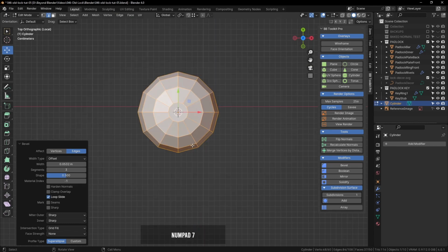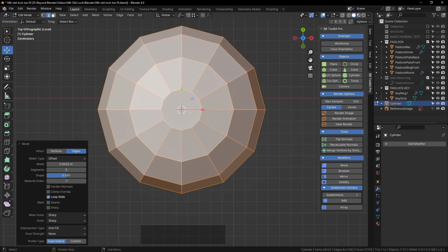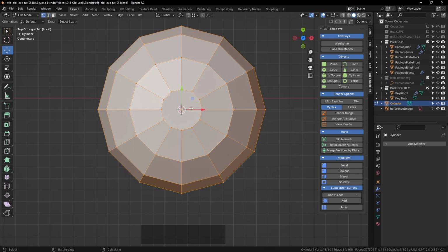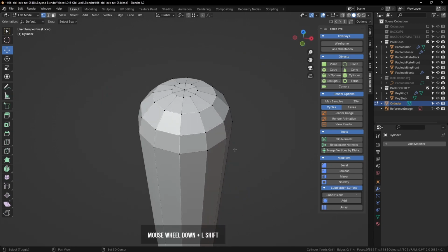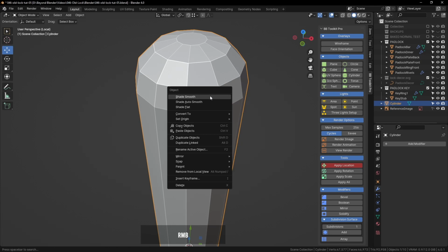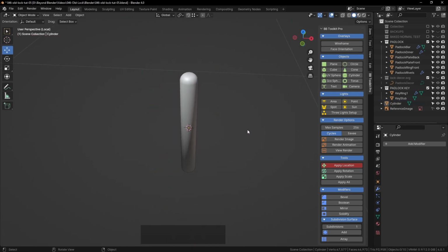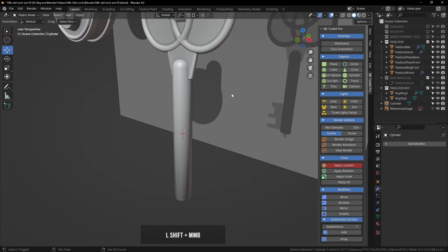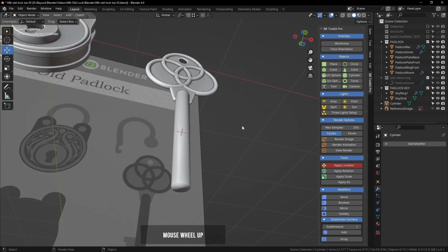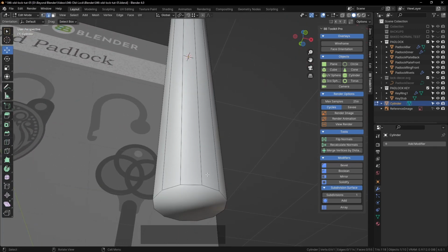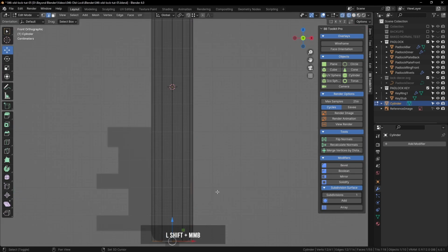That's good enough. And whilst I'm here, I'm switching to the top view with 7 on the numpad, which I set correctly this time. Brilliant. Select these 2 vertices, press J to join them, and then every other vertex and join them. And that gives you some nice quads to top off that part there. Shade smooth. Okay, that's fine. It will look a bit weird with the shading, but that's okay. That will fix itself soon. Let's concentrate on the bottom one now.